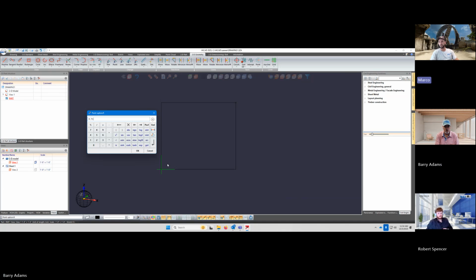Do you have to do decimal or can you do a fractional number? No, you can do a fraction. Only thing I'm thinking is you may need parentheses around it. You can try it and see if the space is enough separation or not. I'm curious. Let me try that. Did I leave that R in there? Yeah, R stands for relative coordinates. So these coordinates are in relation to that reference point that you did just a moment ago.